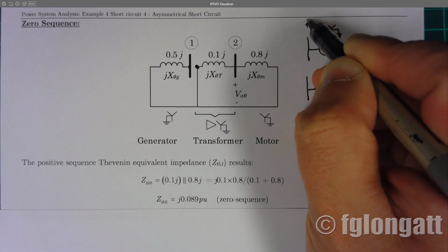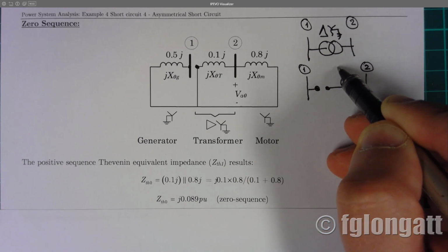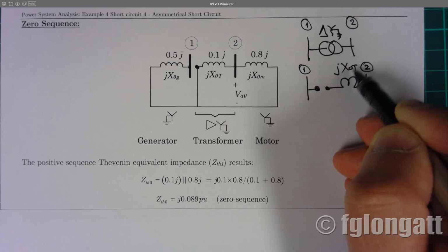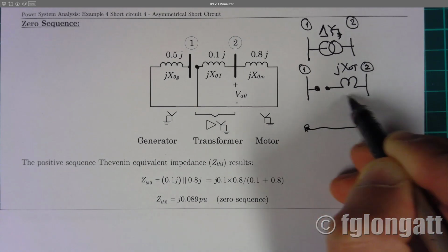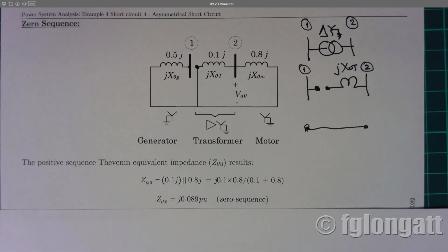Here we use the zero sequence impedance, or zero sequence reactance in this case, and this is the model that we use. I highly suggest to my students that you must check the zero sequence representation of two winding transformer connections. You must be aware about that. It's extremely important that you know the circuit representation of the two winding transformer when you are calculating a symmetrical fault.